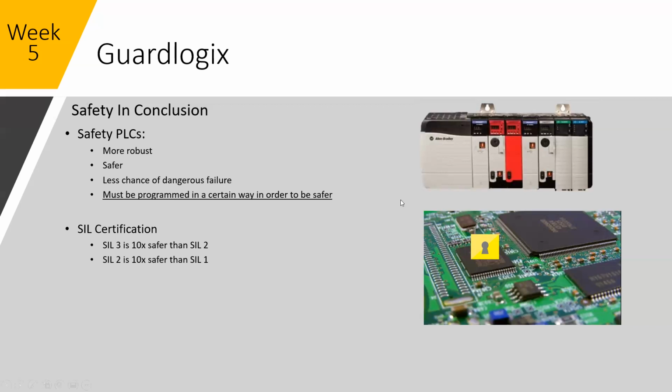So in some motion control, yes, you can justify some of the safety stuff, but if you're just opening and closing valves, turning pumps on, monitoring small pressure systems, you do have to weigh the pros and cons of going down the safety rabbit hole. Okay.